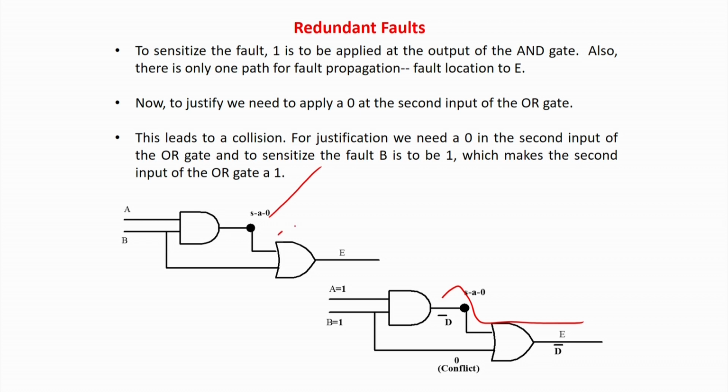But if there would have been many fan outs, then it would actually have been a real soup, because you have to try so many paths. Maybe I am assuming that there was no other path from which the fault could be successfully propagated and justified. I am making that assumption, but only after a huge number of iterations would you have been able to conclude that. Not a good way of handling.